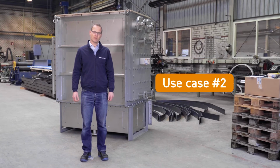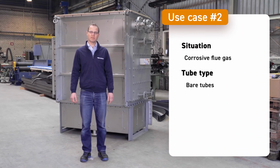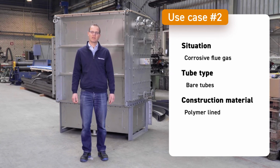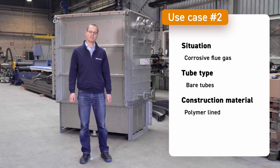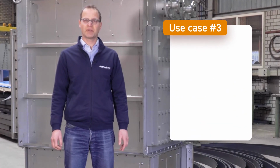The second case, where you expect corrosion, it's better to use bare tubes because fins tend to corrode away, and use a material of construction that can deal with the environment that's present. So if you cool through the acid dew point, you should go for a polymer lined type of system that can resist high corrosiveness. The third usage case is a heavy fouling circumstance.